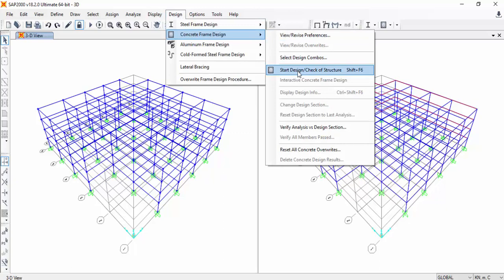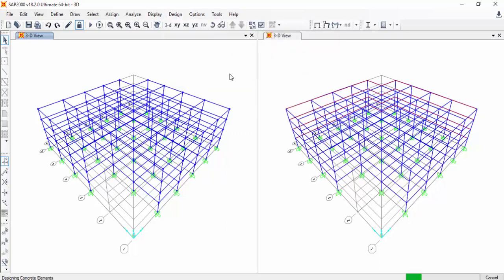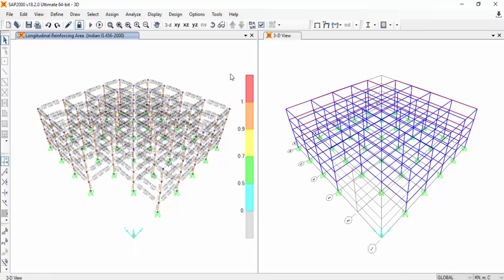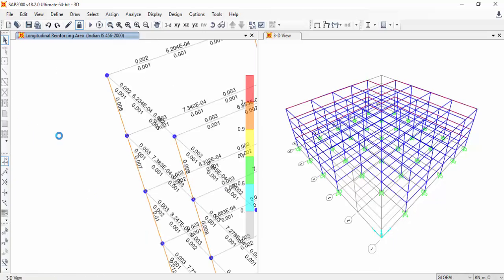Many among you might have understood by this time that when we reduce the stiffness, then time periods will get elongated. And the dynamic base shear would be different in this case from the previous one. So we must also match the dynamic base shear with static base shear. Although we are not doing it here because our purpose is to show you how the presence of P delta analysis affects the column design.